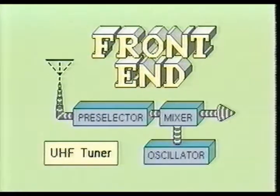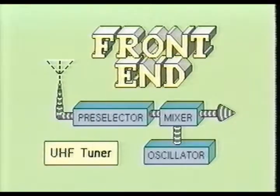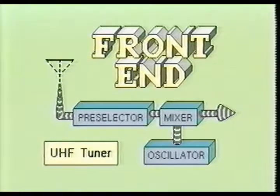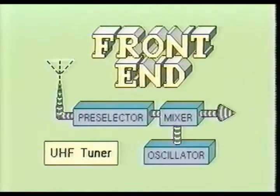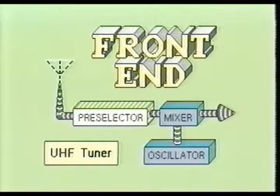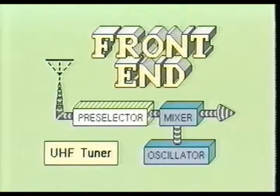Here you see the block diagram of a typical UHF tuner stage. Notice that it consists of a preselector section, a mixer section, and the oscillator section. The preselector portion of the UHF tuner must satisfy three requirements. First, it must have a bandwidth of 6 MHz and be able to select the desired channel. Second, it must reject all unwanted channels. And third, it must isolate the oscillator stage from the antenna.